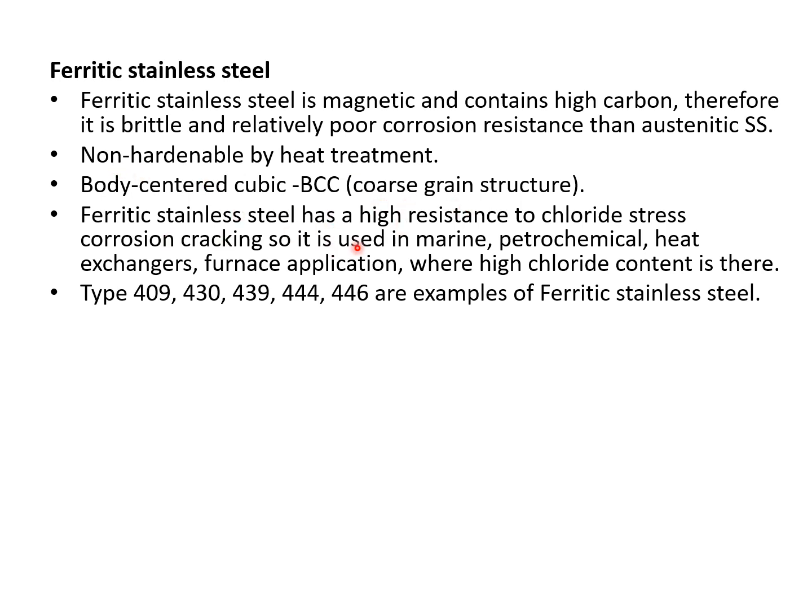Ferritic stainless steel has a high resistance to chloride stress corrosion cracking. So it is used in marine, petrochemical, heat exchanger, and furnace applications where the chloride content is there. Some of the examples are 409, 430, 439, 444, 446.